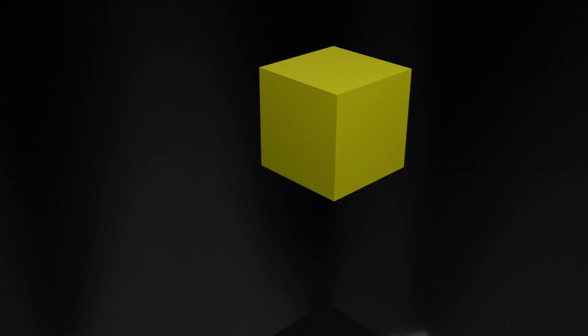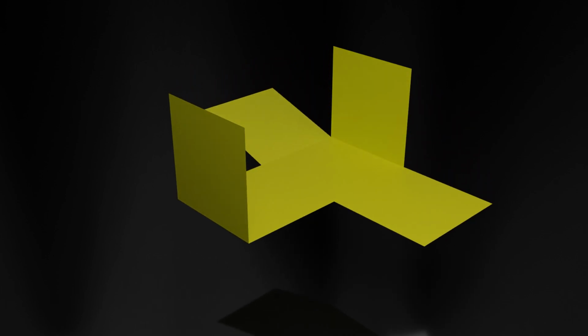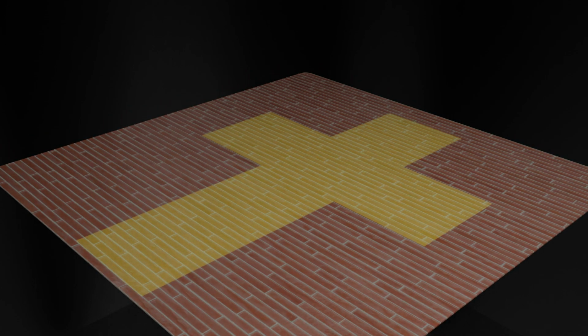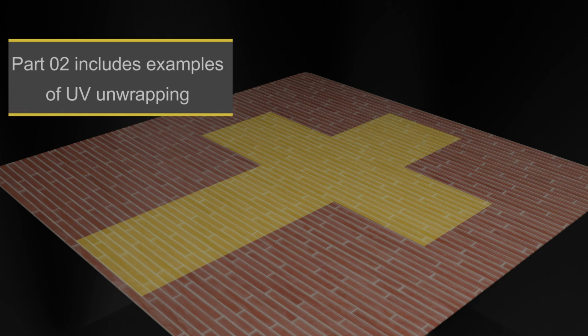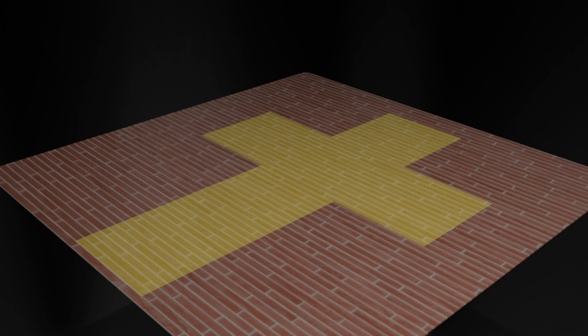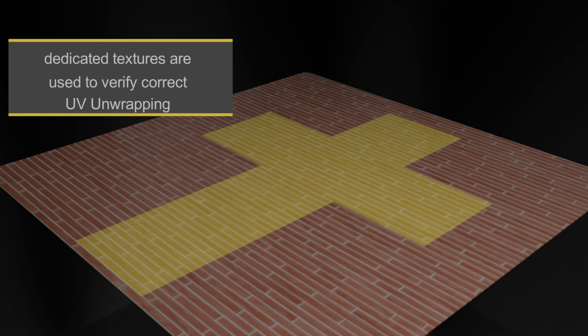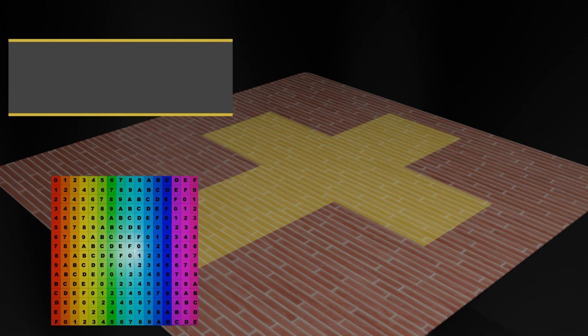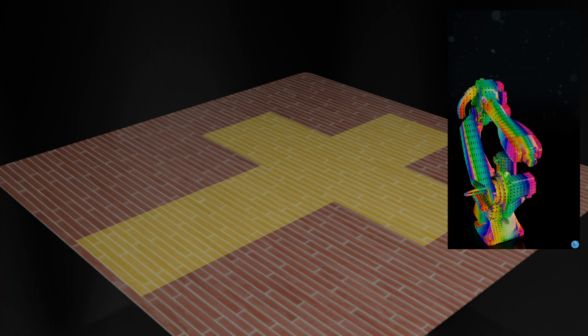We can view this as follows. Let's take a look at the same cube again, and what we want to do is open this up or cut open the top and lay it down as a 2D object. So lay it down on the floor. Then we are going to apply the texture, and in this case we have the same texture again coming in from the top, and we're going to place it over the 3D object which we just laid down as a 2D object. Then we can get all the orientation correct and the positioning as well, and once we have done that we can reapply them together so the orientation and the position of the texture on the 3D object is correct, and we can wrap it up to create a 3D object again.